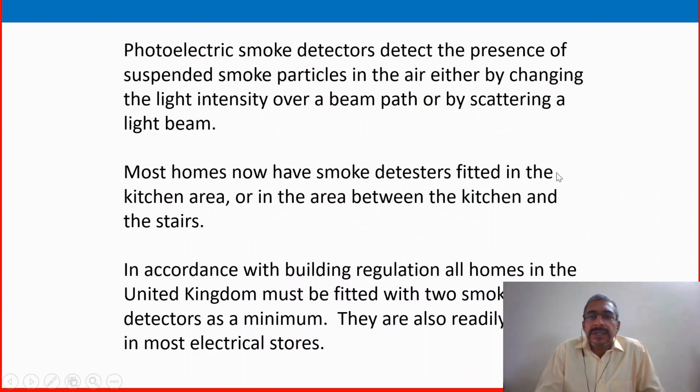Photoelectric smoke detectors detect the presence of suspended smoke particles in the air, either by changing the light intensity over a beam path or by scattering a light beam. Most homes now have smoke detectors fitted in the kitchen area and the area between the kitchen and the stairs. In accordance with the building regulation, all homes in the United Kingdom must be fitted with 2 smoke detectors as a minimum.